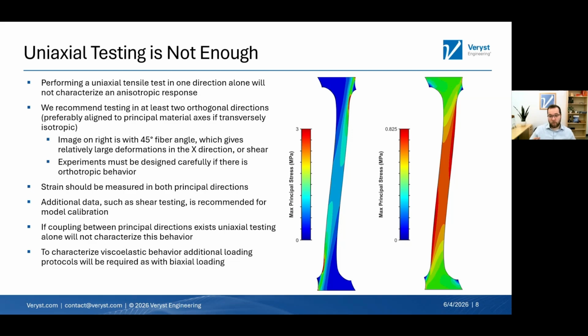The image on the right shows what happens if you don't do that. This is at a 45-degree angle, with a Holzapfel-Gasser-Ogden material model, which, for those unfamiliar, I will talk about more later. This is an anisotropic constitutive model, and we provide a 45-degree fiber angle. And we can see the test in a stiffer and a more relaxed, more compliant material.